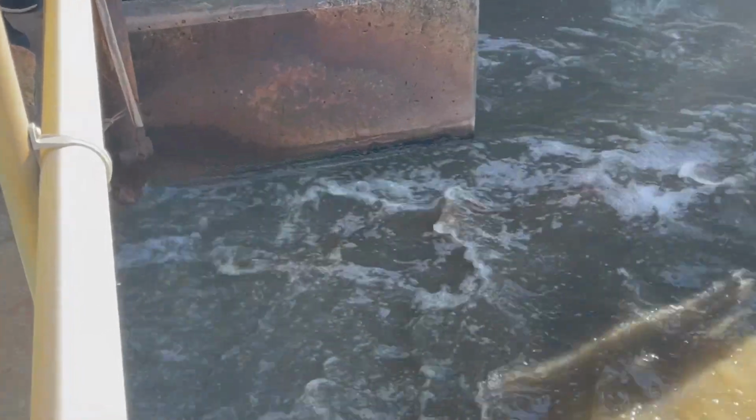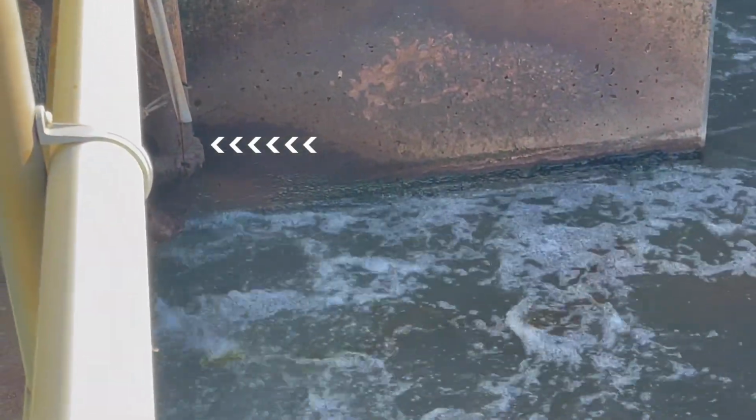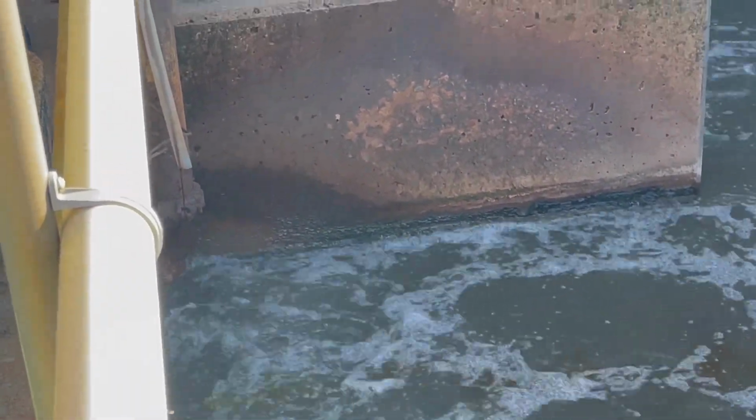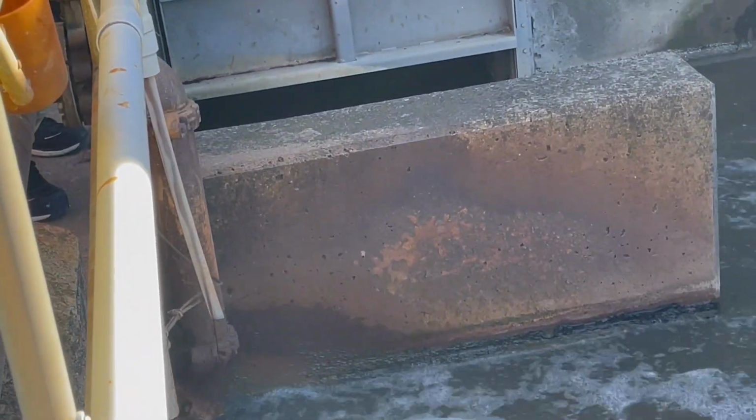As you can see, there is a small pipe continuously adding a brownish yellow colored liquid chemical into the grit removal pool. This chemical is called ferric chloride, and it helps smaller solid particles aggregate together so that they can settle at the bottom of the pool faster, and so that it is less likely that many small solid particles will be left in the wastewater pool. It is also very common for plants to use aluminum chloride instead of ferric chloride to perform this step, which is called coagulation.